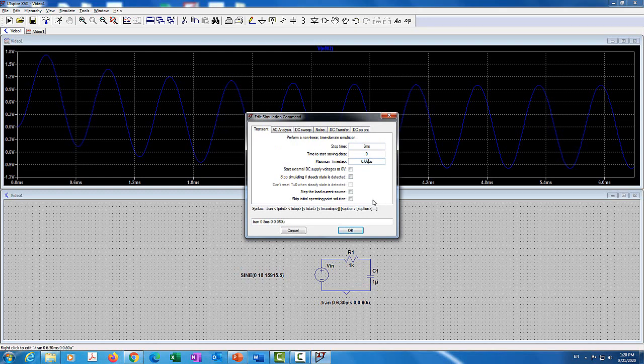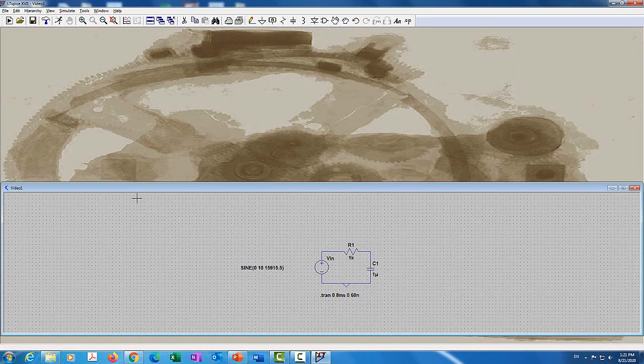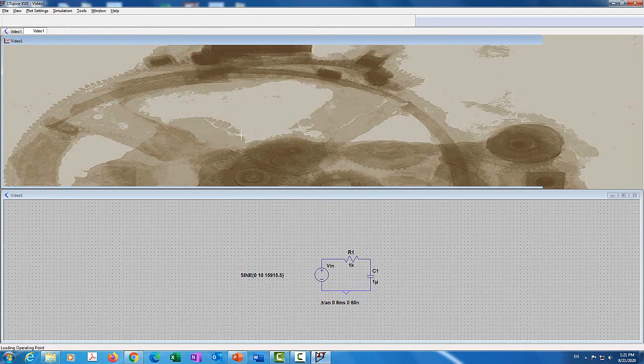And remember that the frequency now is faster, so I'm going to reduce the resolution even more. So it's going to be 0.6 microseconds, so the resolution here is going to be 6 nano. So I'm going to run it for a longer time to see that transient effect. And then I need to lower the step size because it is a higher frequency. Let's close this. Save, run.